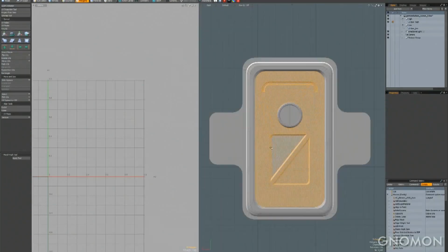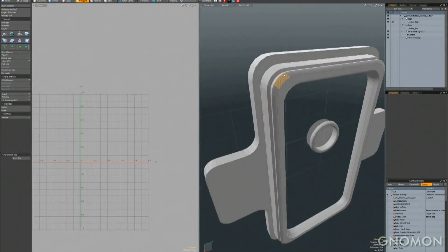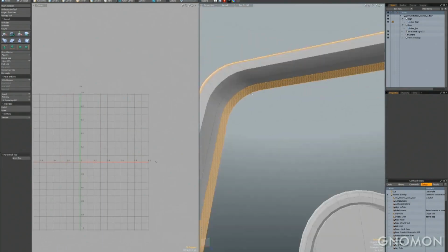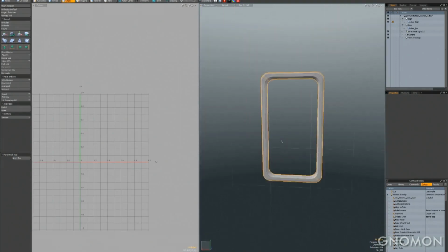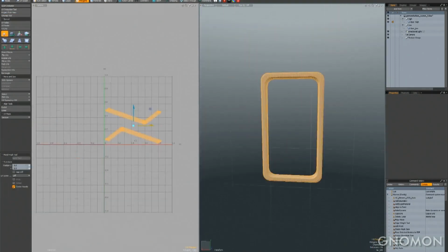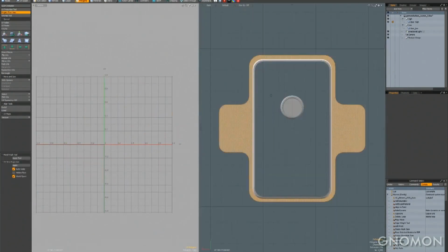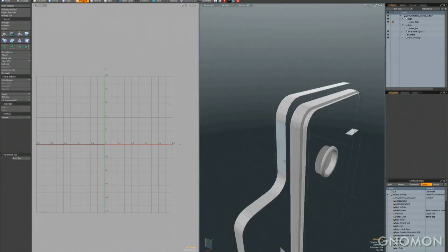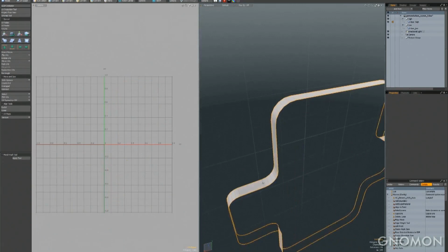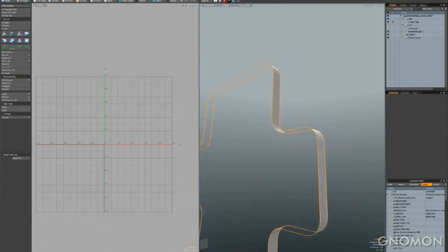For the UV tools, these are absolutely one of the best parts of Modo for me. Super easy to use. I use about 4 total, and I have them all in a pie menu. This one in particular, you can take anything and make it a perfect rectangle, with perfectly spaced edges, perfectly unfolded. That's completely invaluable for stuff like strip texturing when you're working in games and you have a lot of modular textures with different broken up sections that you need to wrap across a bunch of geometry.